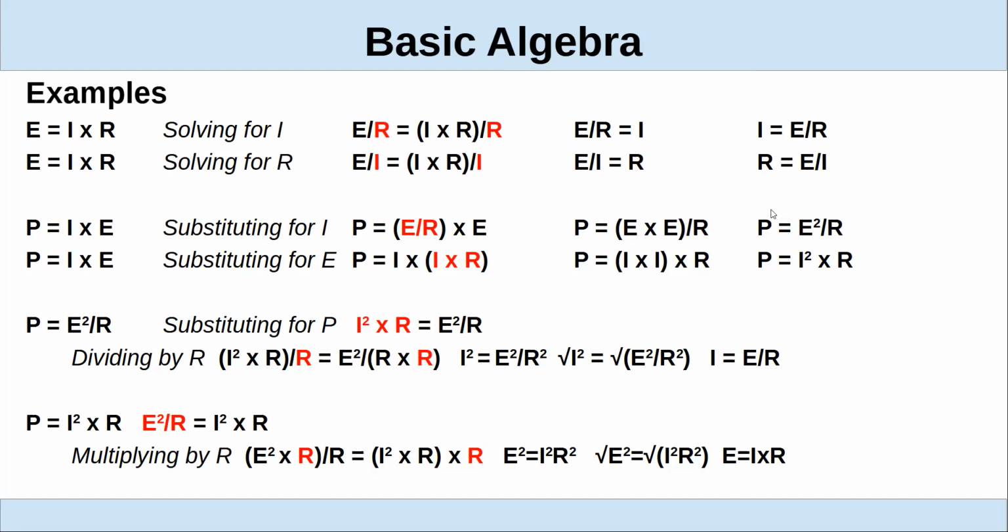There's another pie chart for this one also, where you do the same thing with power, current, and voltage. And a lot of times you need to solve it for voltage or current. And those, if you notice, are always a square function. And that'll come up a little bit later when we talk about decibels, on why when you're doing decibels on voltage or current, it's 20 times the log as opposed to power, where it's 10 times the log. It's because of the square function.